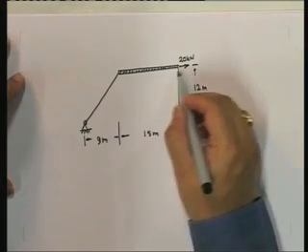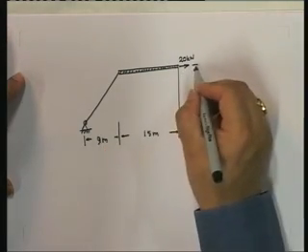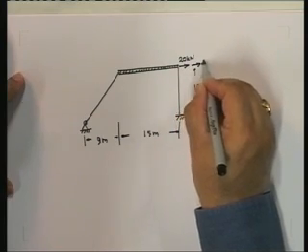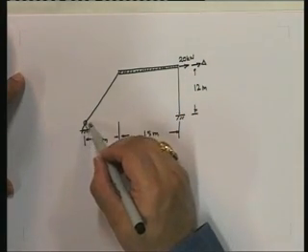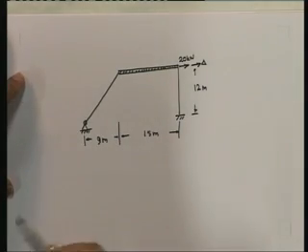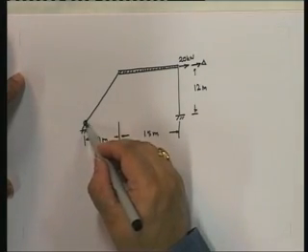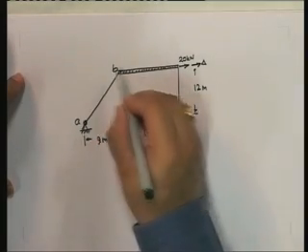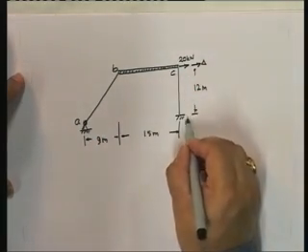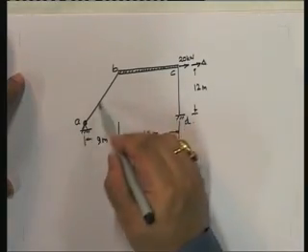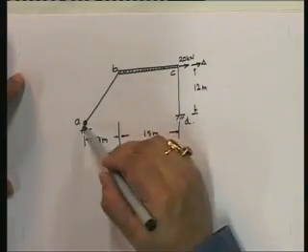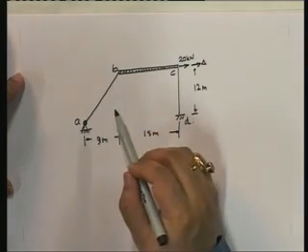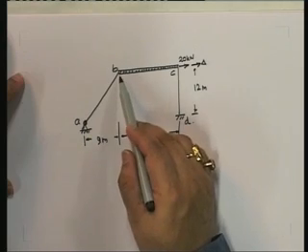Under normal circumstances, you will see that this has 2 degrees of freedom. 1 degree of freedom is this lateral displacement, and 1 degree of freedom is the rotation at this hinge. However, since this is an end hinge, I am going to consider this AB member as a modified member, so that I will write down the modified member force deformation relationships.